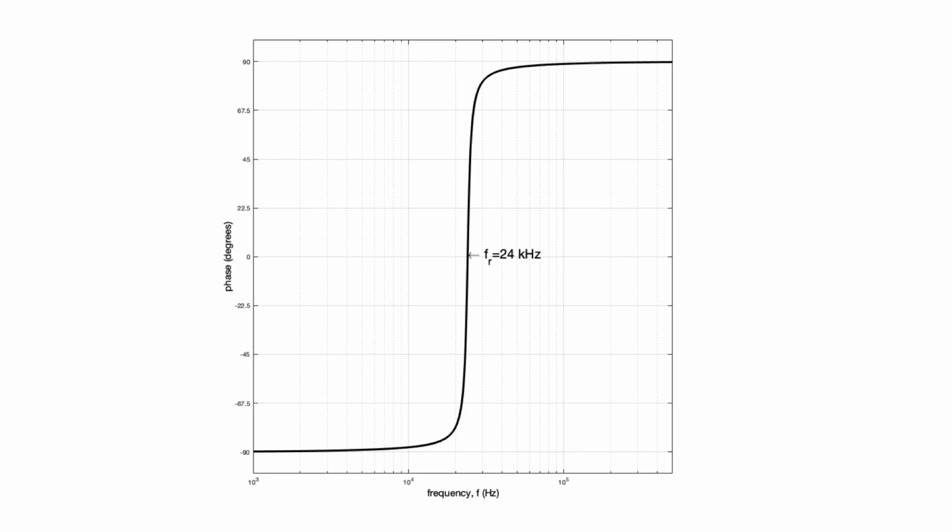Finally, we take a look at the phase angle as a function of frequency. At the resonant frequency, we already know that the phase angle is 0, since the reactances cancel each other out and the impedance is just equal to the resistance.